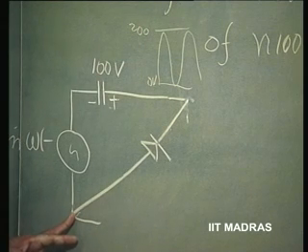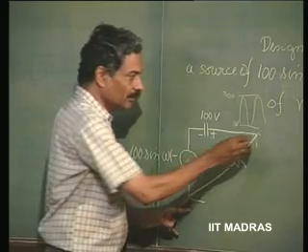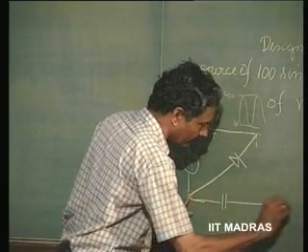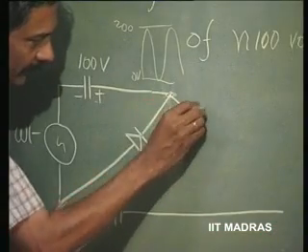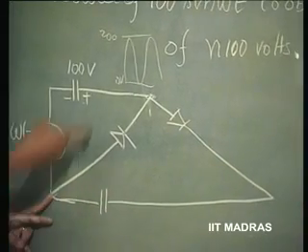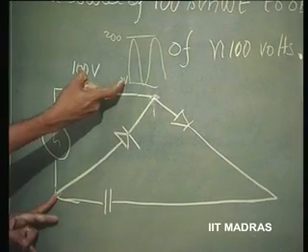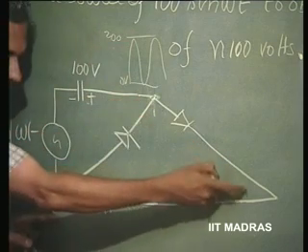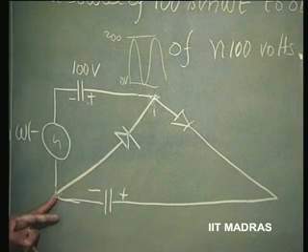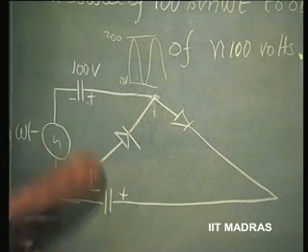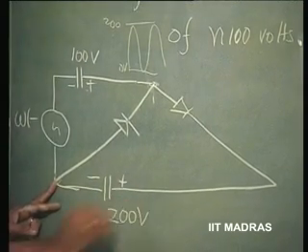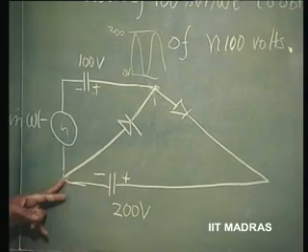So, this can be again used as a peak detector now by putting a capacitor and a diode in this direction, so that this circuit, which gets an input which is varying above 0 going up to 200 volts, can get this as the input and charge this capacitor to the highest positive peak here, which corresponds to 200 volts. So, the capacitor gets charged to 200 volts.